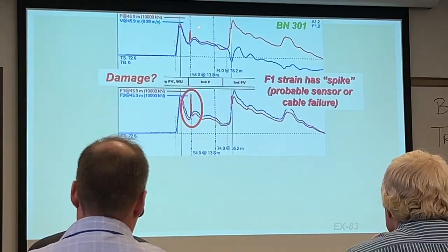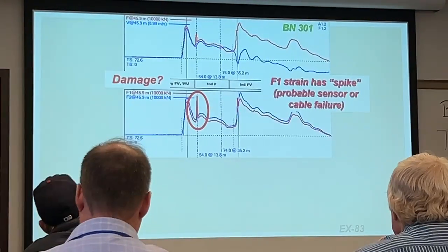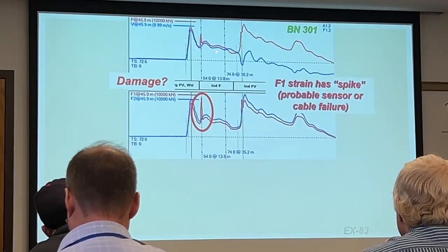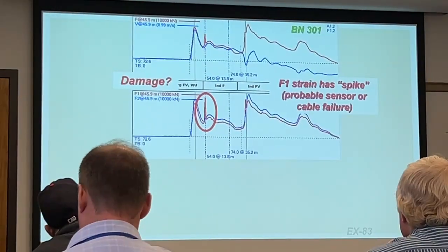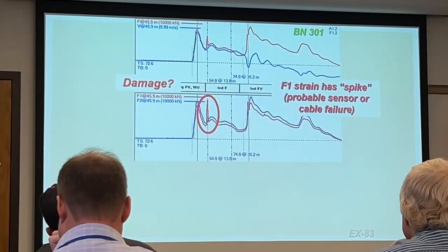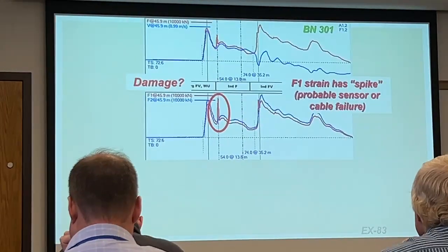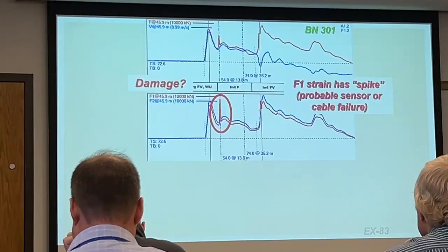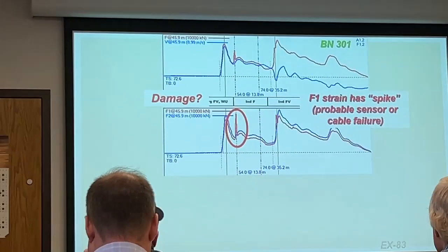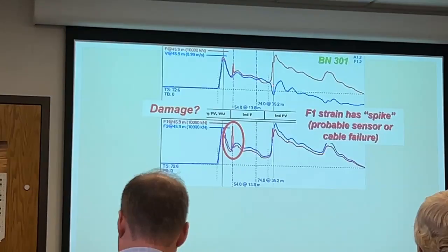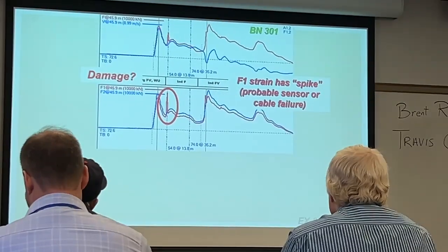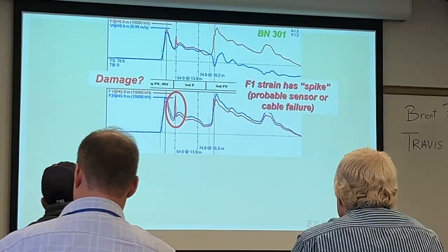If we look at the second damage indicator, there we see our force dropping off and our velocity increasing. So that starts to look more like a free end. Remember, we said a free end condition is the force dropping to zero, the velocity rising. This is a free end condition that's happening early, or the beginnings of a free end condition that's happening early. And so this is an actual reduction in cross-section. And so that actual reduction in cross-section is likely an indicator of damage.